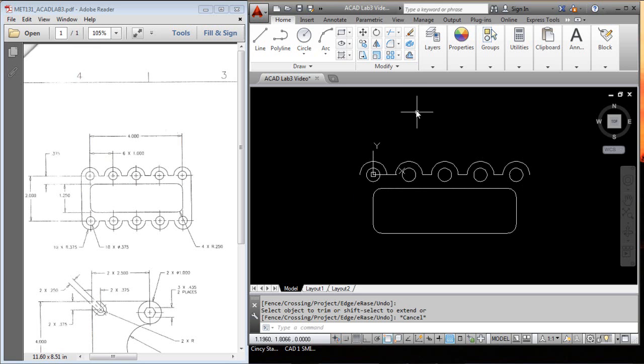Now we might have been able to do that just a little bit easier. Let's go in there and hit trim again. So let's go here, grab that. Now note down here, if we hit edge, we're still at extend. So that's why this will work, because we're extending that line into infinity.